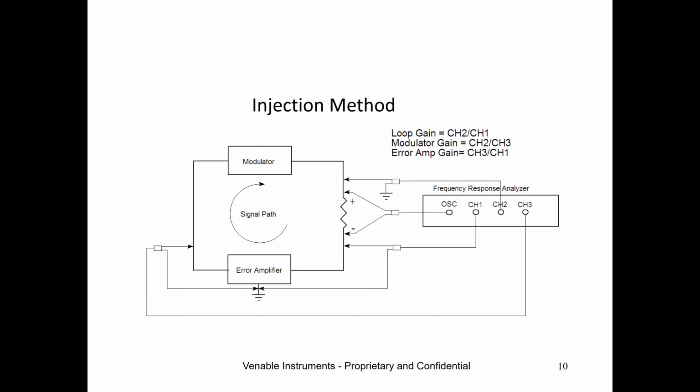Yeah, well, basically you would have to measure the power stage first, if you want to change the compensator or error amplifier, because that's how it works. You've got the power stage. There may not be much you can do to change the power stage. And then you use the error amplifier to get your gain and crossover, if you understand where I'm going.